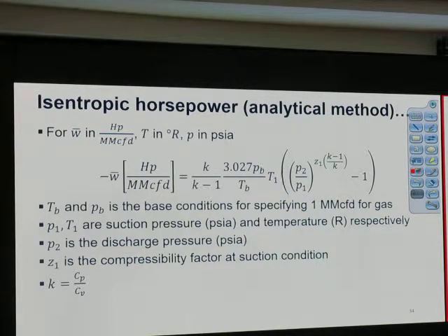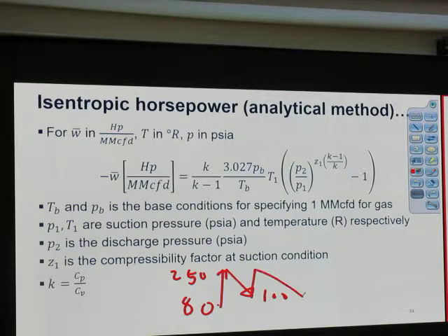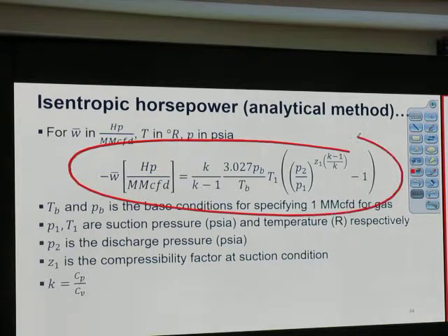So even though we start at 80, the temperature goes up to 250, we go down. Maybe sometimes the interstage cooler doesn't cool that much and it becomes just 100. We compress it again, we cool down again, we try to cool down to the same temperature. The reason it's the same temperature is because we use the same compression ratio per stage. Okay? Alright. This is per stage. If you have multiple stages, add them together. If you don't have any number given, just the inlet temperature, you may assume 100 F.